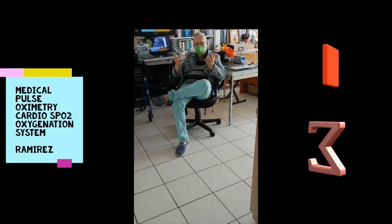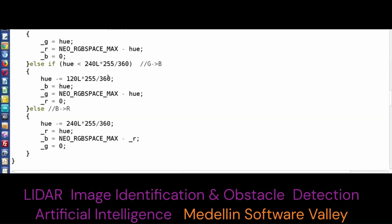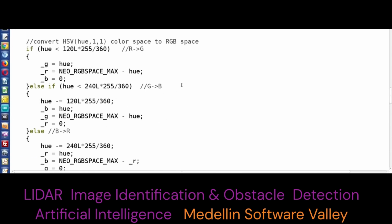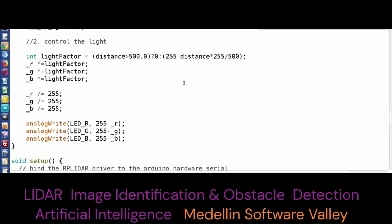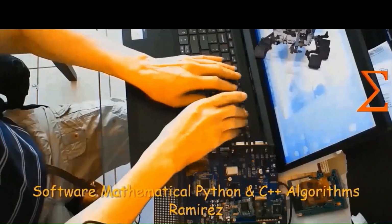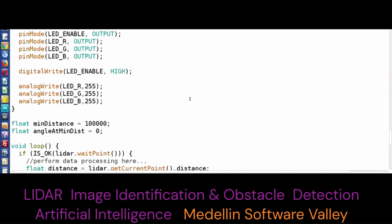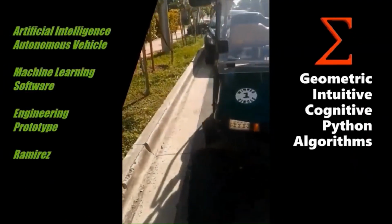Therefore, the sensor's calibration is done in the function without bias. As you can see in the software models presented in the video, the calculated distance is displayed on the main CPU subsystem serial monitor. A 10 millisecond delay is used after every scan to prevent any crossover or collisions.